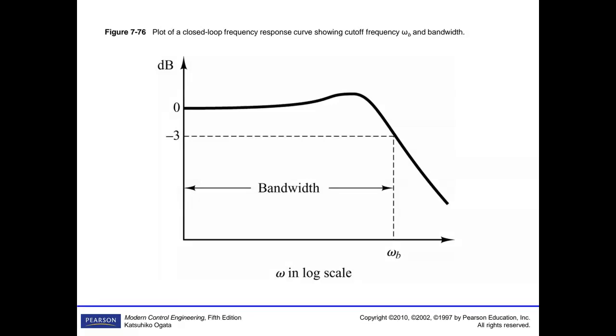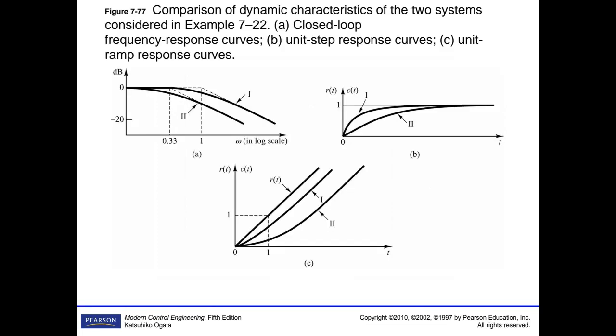So we have just reviewed what the Bode plot is all about and how we could draw Bode plots. And also we can design our control system by using Bode plots, which I haven't given enough emphasis on. However, you can continue if you want in your engineering life. The phase margin and gain margin are important parameters for the Bode plots.